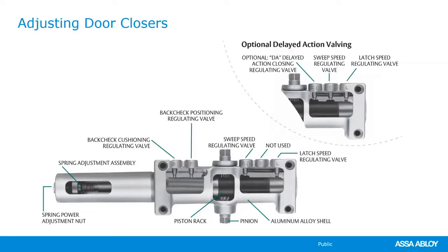Well, air is compressible, so as soon as we get to the latching valve, that door is just going to slam. And again, if you're an end user, it's a liability for you, where that slamming motion, with a big heavy door and a big heavy spring in that door closer, can catch somebody. It can hit them in the head, or catch their hands. So definitely leaking door closers we need to replace.